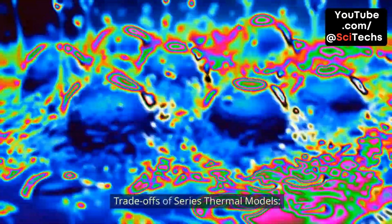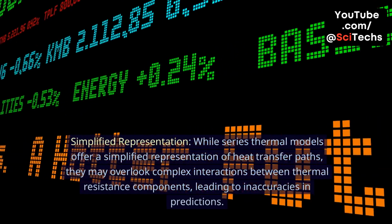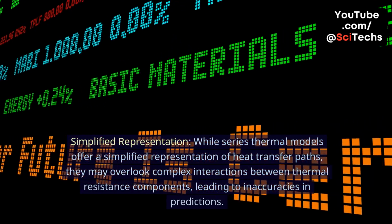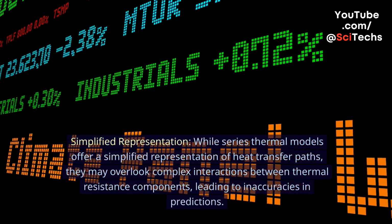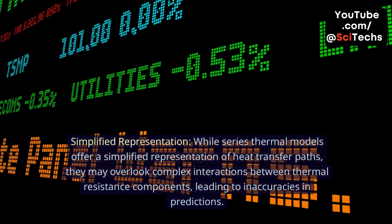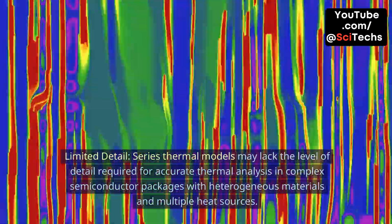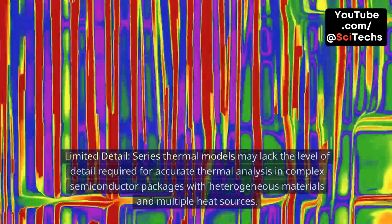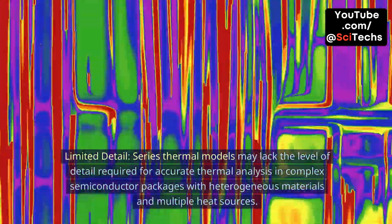Trade-offs of series thermal models. Simplified representation. While series thermal models offer a simplified representation of heat transfer paths, they may overlook complex interactions between thermal resistance components, leading to inaccuracies in predictions. Limited detail. Series thermal models may lack the level of detail required for accurate thermal analysis in complex semiconductor packages with heterogeneous materials and multiple heat sources.